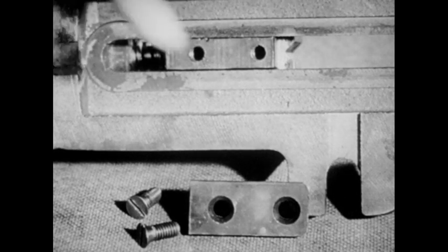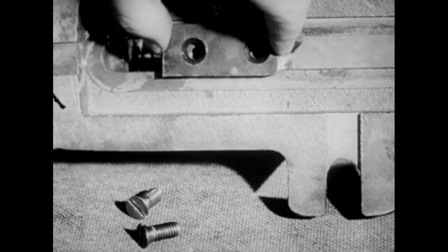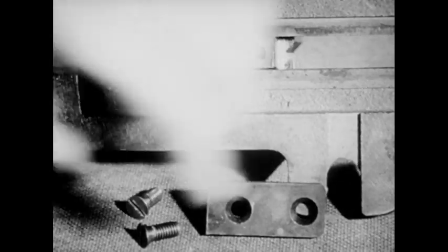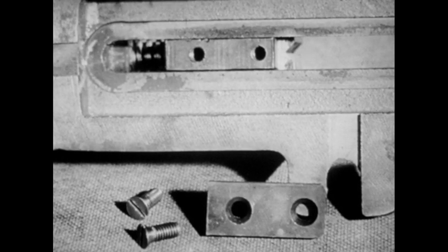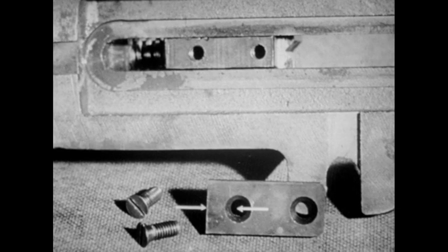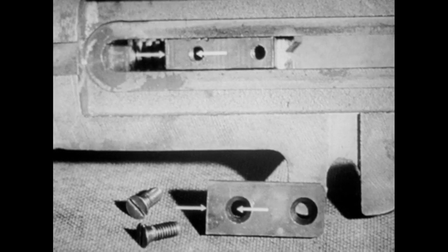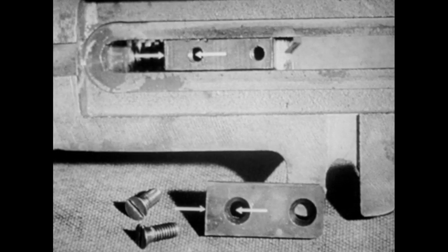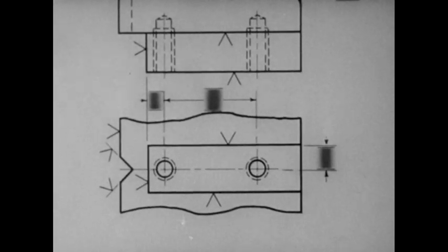In order to position the plate and the movable jaw tongue lengthwise, the screw holes must also be located from the ends of these pieces. Give the distance from the center of one hole to the end of the plate and the distance from the center of the corresponding hole to the end of the tongue. Show these dimensions for the movable jaw on the partial bottom view.